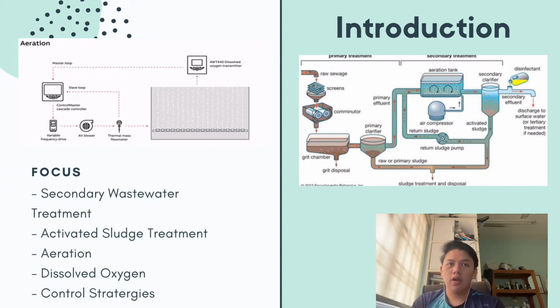On the other hand, when the concentration of dissolved oxygen is higher than the optimum range, the energy consumption will become high because the aeration equipment needs to carry out unnecessary usage. An unwanted microorganism reaction will be promoted. Hence, it is important to implement a control strategy to regulate the DO concentration at an optimum level. There are several approaches to categorize the control structures of aeration control, but only the dissolved oxygen cascade control will be highlighted in this presentation.